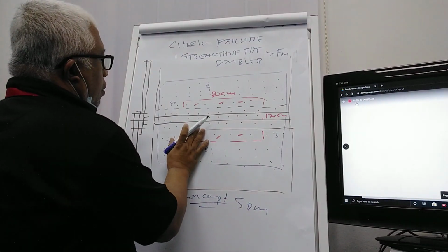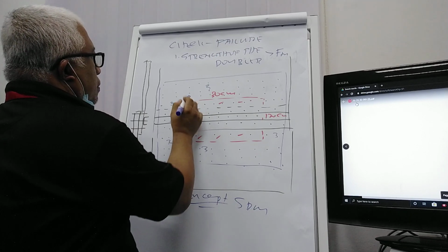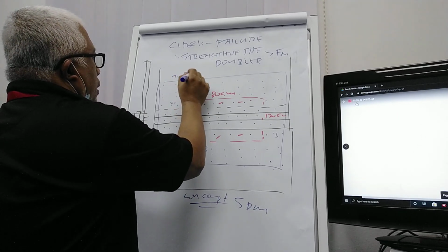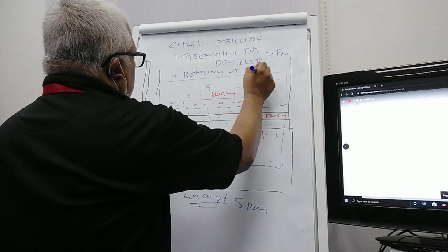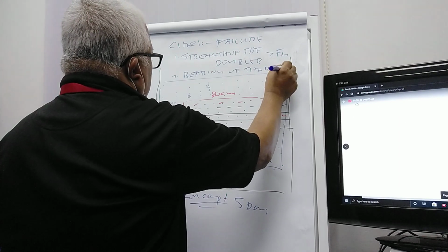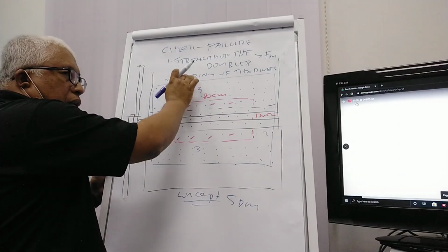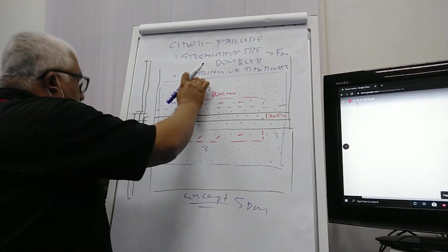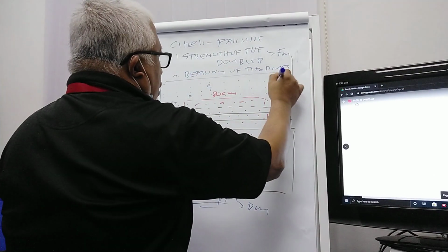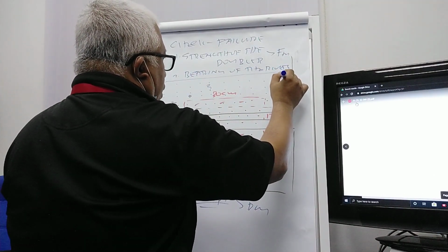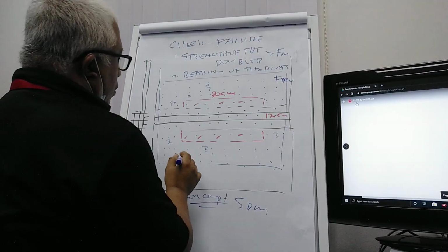Then you have to check bearing of the fastener. So bearing of the rivets. Again, the bearing stress of the rivet should be less than the material bearing, FBR, FB bearing ultimate.